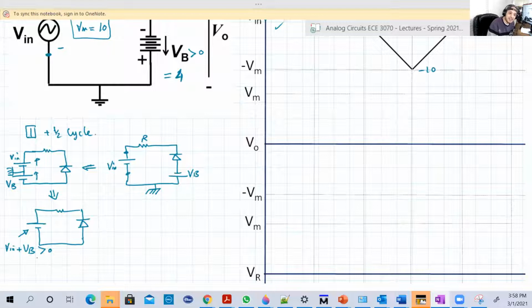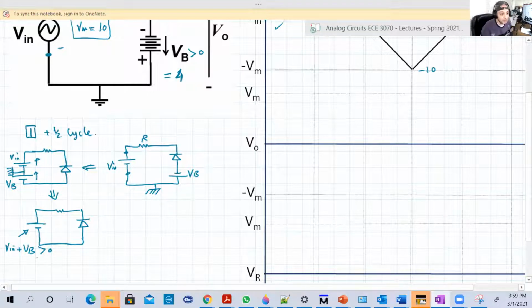So now we can see that the diode will be reverse all the time during the positive half cycle, because its N side is closer to the positive terminal, and its P side is closer to the negative terminal. It's actually connected to the negative terminal. So it's reverse. Or you can say this battery wants to push current out of the positive terminal, and the current cannot move from N to P in the diode. So the diode is reverse.